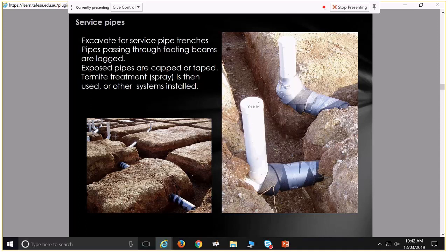But your standard sort of house has things like timber architraves, and termites can even eat the paper on your gyprock. Not that that's a particularly common thing, but there's lots of little timber bits and pieces around your house, or your cabinets and things like that. Even your grand piano, you don't want termites eating those things. So if we look at the NCC, it tells us that we have to protect against the primary building elements of the building. So if it's a steel framed house that doesn't have any other edible primary elements, then we don't have to protect against termites. But it's really quite a good thing to get your termite protection in there anyhow, because there's going to be other timber elements inside the building that termites will want to eat.